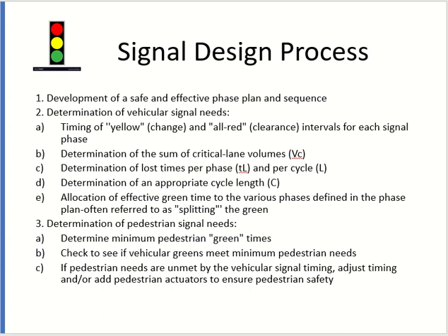The third step is for pedestrians. It is only done when pedestrians are available and they are allowed to cross the intersection. Obviously, if pedestrians are available, then the signal becomes very easy and safe for them to cross, right? So normally we allow the pedestrians to cross at the signals, but they should be there. If there are pedestrians available, then you should know how much time they need to cross the road. First of all, calculate the required time by the pedestrians. Then cross-check with the signal timing.